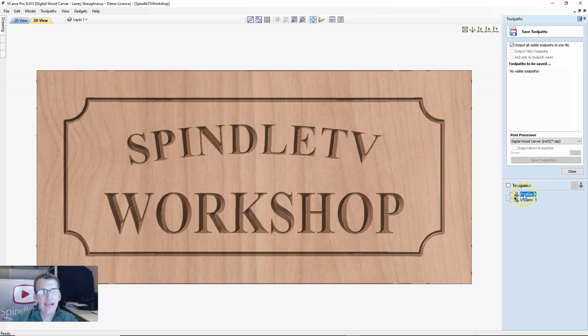Now, because I have two toolpaths that use the same router bit to carve, I can save them as one file. If each of these toolpaths used a different bit, then I would have to save each file separately. But since they are both the same bit, I can check off up here that says output all visible toolpaths to one file, and then I can make the toolpaths visible by clicking on the two toolpaths here, putting that check mark in, and notice now it lists both of them in the toolpaths to be saved area here.